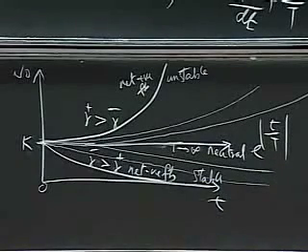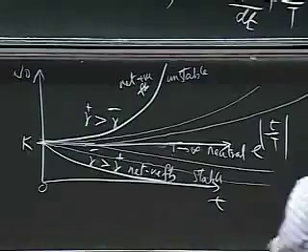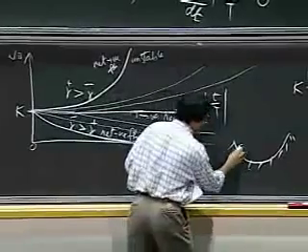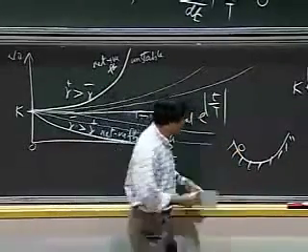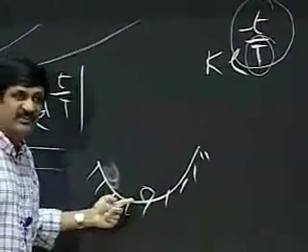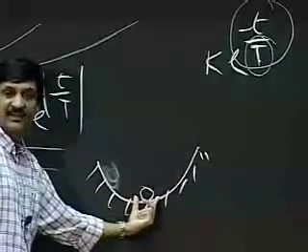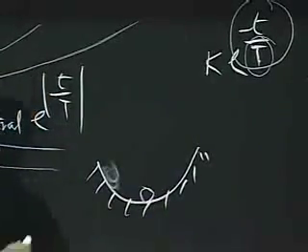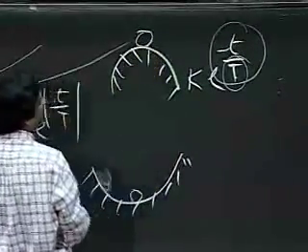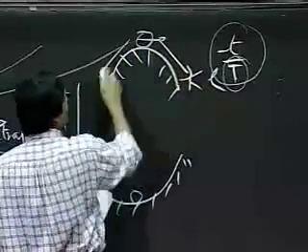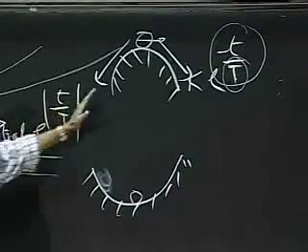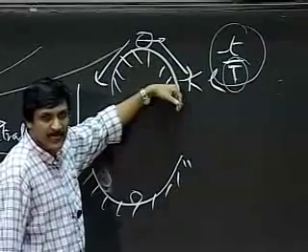And there is a mechanical analog to all of this. You can show that this situation is akin to adding a physical well of this sort and a ball in there, and letting the ball go. Then the ball will come down here and settle down in a stable state. Any small perturbation of the ball will get it to come down and settle down here. The unstable situation is where I have a ball sitting up here, where any small perturbation will get it to zip down to a positive rail or to the negative rail. So this is an unstable equilibrium situation.